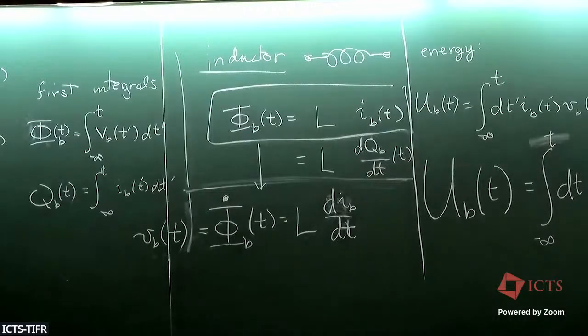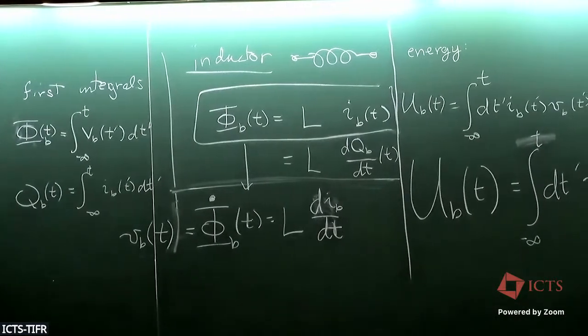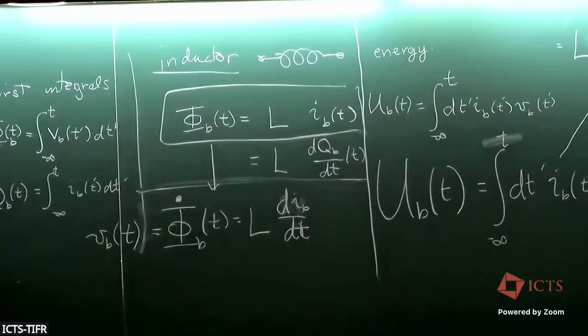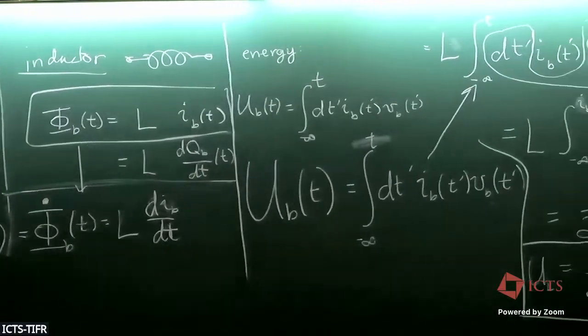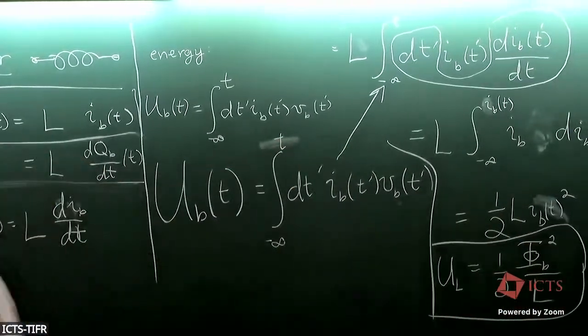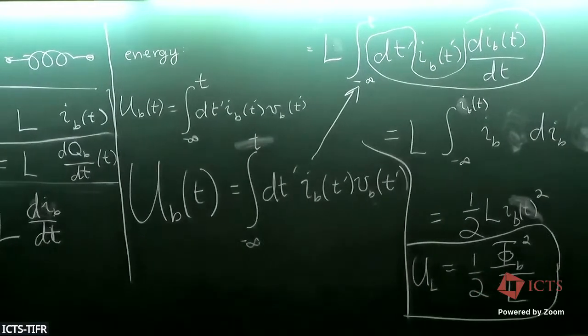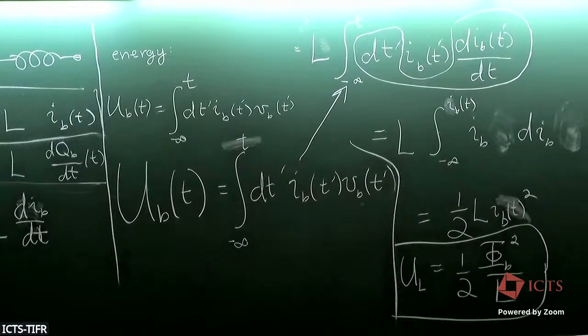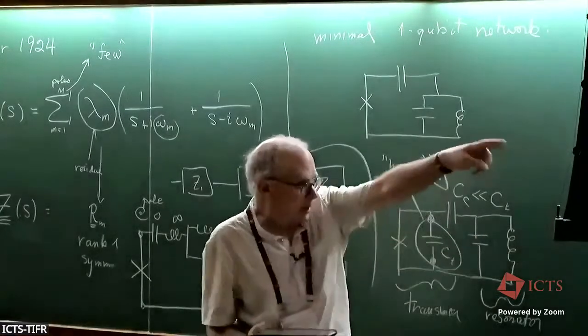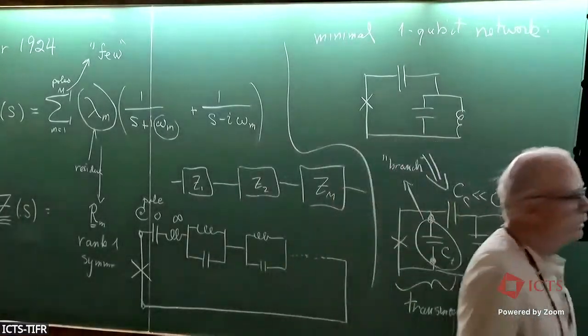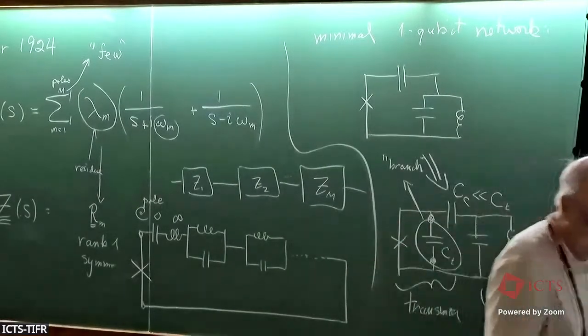And so I've succeeded in deducing a contribution to the potential energy of the Lagrangian. And it says for each branch, I just go into my circuit. Every time I see an inductor, in this one I only see one at the moment, I say, energy, check, and it's related to this branch variable in the way I've just shown.